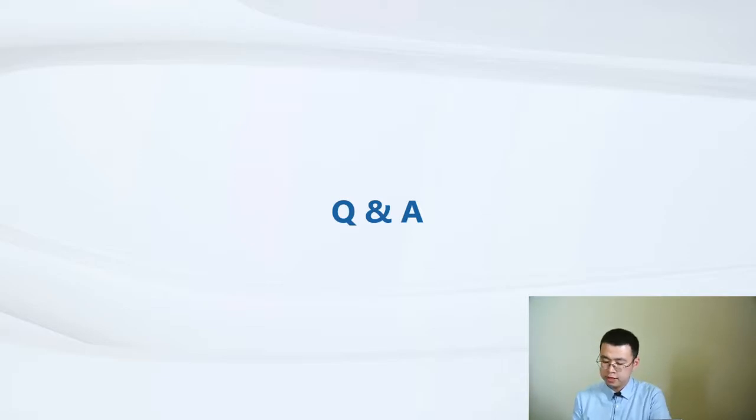And someone wants to know if I change the size of a product, can the toolpaths be updated automatically? Okay, this is a question about the CAD and CAM modules getting together. If you change anything in the CAD module, it can easily transfer to the CAM environment. And during this procedure, you can immediately see the difference in the CAM environment. And what you should do is to update the toolpaths by yourself, since some CAD changes may be very slight.